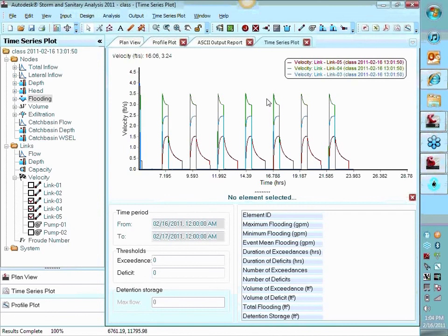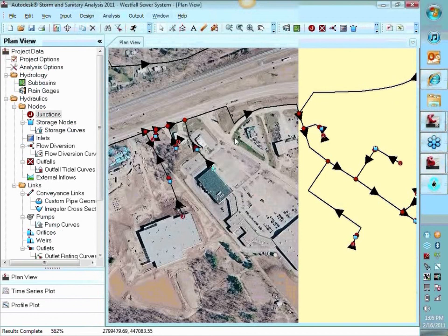That's essentially it. That's the crash course on low pressure systems. If you think about it, there's really not too much you can't model with this. I'm drawing a blank on what you can't model with this. It does all the nutrient stuff. It does all the sanitary stuff if you have combined systems, or you're just doing gravity and pump stations for the sanitary side. If you're doing storm and have ponds and weirs and culverts, and it goes out of your system into a channel and then under a road culvert, then back into an inlet, and then goes off to your BMP, you can put that all right in here and just run it all at once. So it's an option.